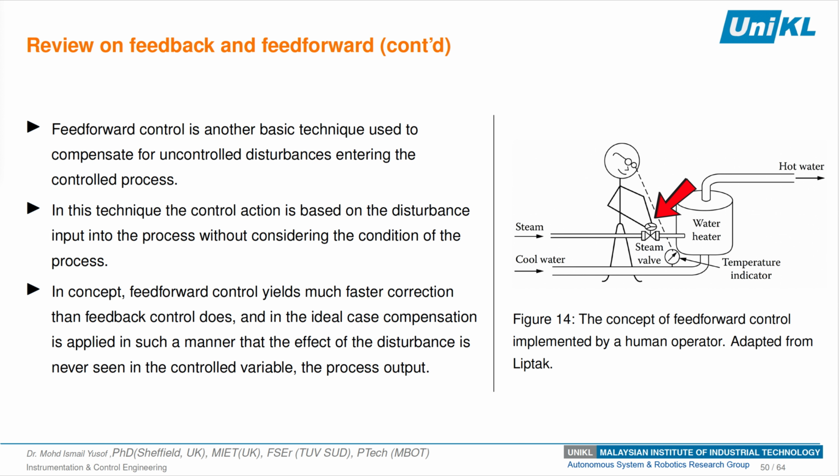It has been found that combining feedback and feed-forward is desirable in that the imperfect feed-forward model corrects for about 90% of the upset as it occurs, while feedback corrects for the remaining 10%. With this approach, the feed-forward component is not pushed beyond its abilities, while the load on the feedback loop is reduced by an order of magnitude, allowing for much tighter control.